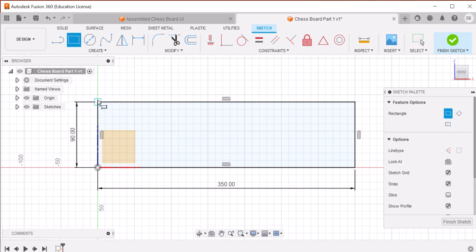We're going to go into the top left corner. We're going to click on our mouse or trackpad, drag out, and remember we always put our dimensions in. So our dimensions here are 19, because that is our material thickness. I'm pressing Tab on my keyboard to toggle between, and if we divide 90 by 3, that is 30.